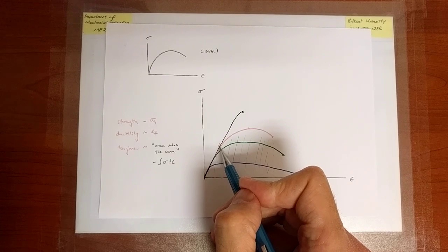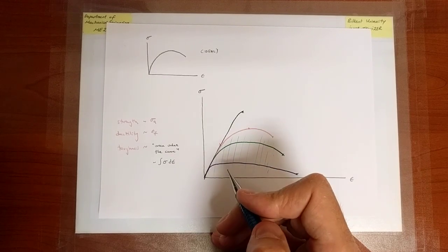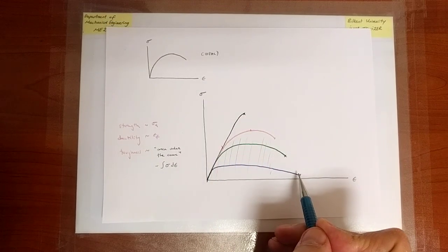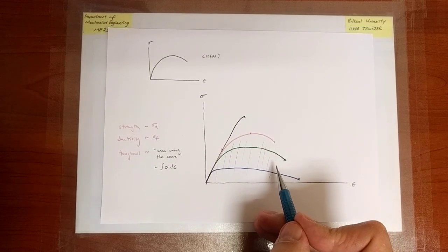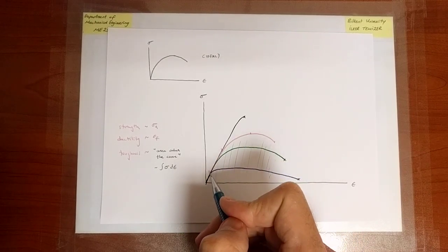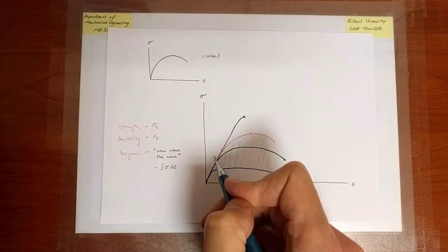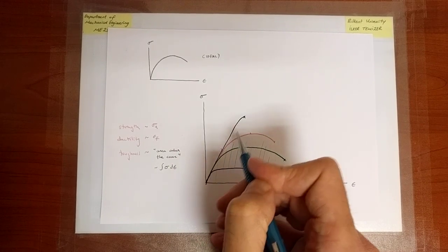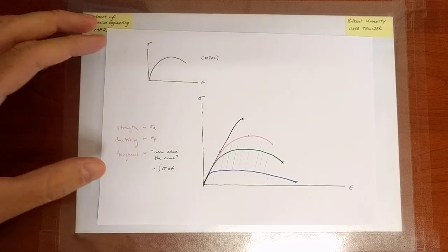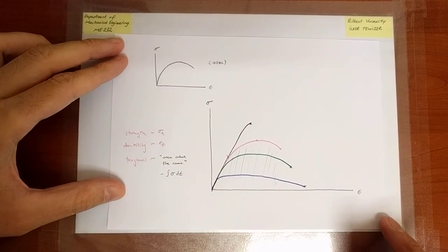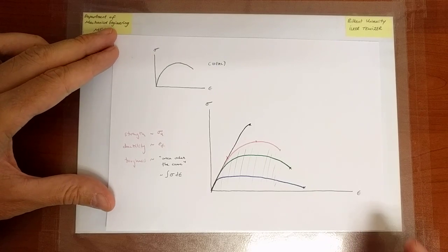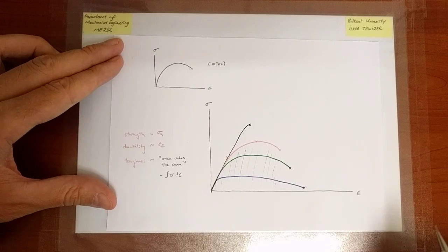Okay. Now, however, the plastic behavior is drastically different. Failure strength is drastically different, and the onset of plasticity likewise is drastically different. In other words, the yield strength is drastically different. Here you see that probably yield strength is over here, there it's there, for red it's here, for black it's over there. So plastic behavior is drastically modified by alloying the metal in different ways. Again, same thing goes for polymers. The way you treat it will drastically alter the polymer behavior.